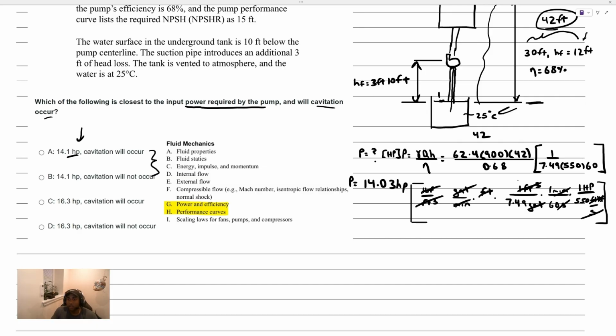So as you increase the pressure of the fluid, which is liquid and vapor at this point, those vapor bubbles are going to begin to collapse, and they end up corroding the impeller inside of the pump, and it makes a loud noise and it causes a drop in pump efficiency. So we don't like cavitation. But that's the idea of cavitation.